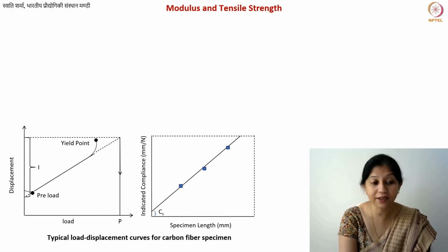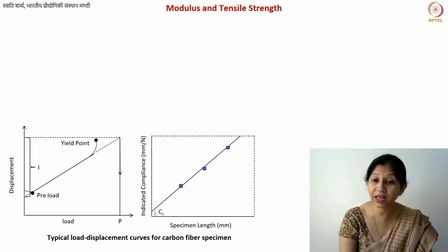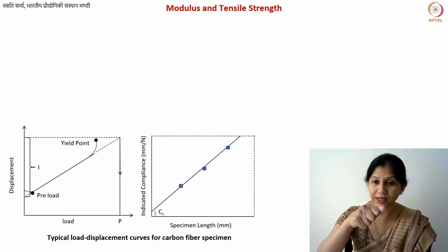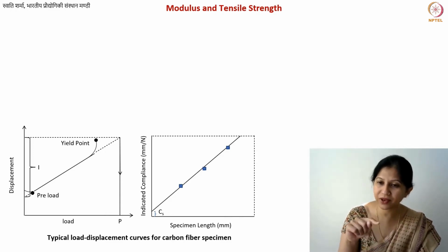This is always the case. You get strain hardening in the case of viscoelastic polymers as well, that we had learned before. What happens is carbon fibers are not like polymer fibers. They do not have the same kind of geometry or the microstructure. However, they do have these long sheet and chain like structures. So they do tend to at some point align themselves, and therefore you may get a little bit of strain hardening, but typically even that is not very significant.